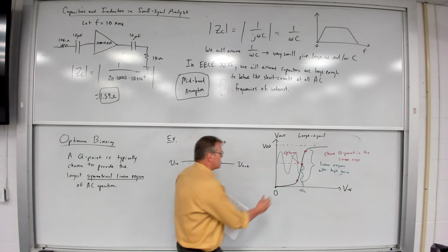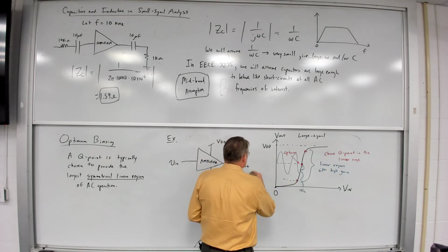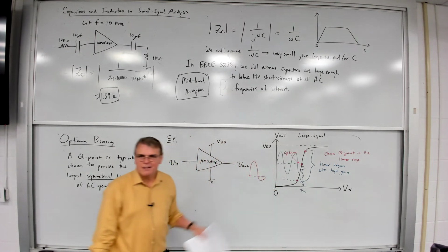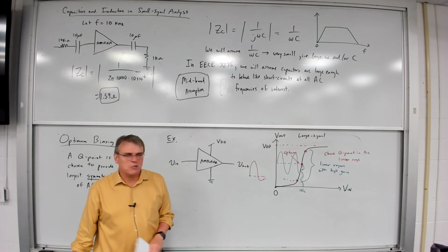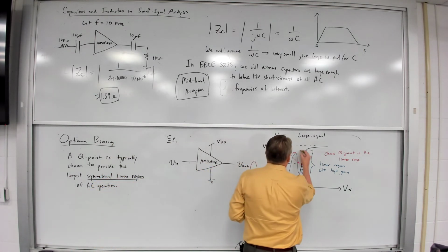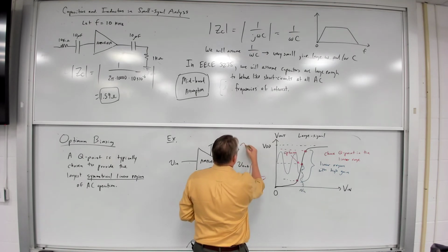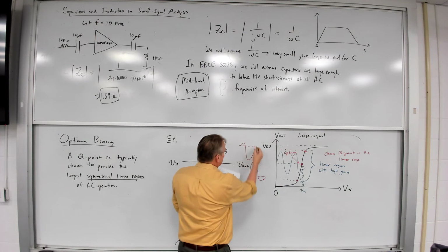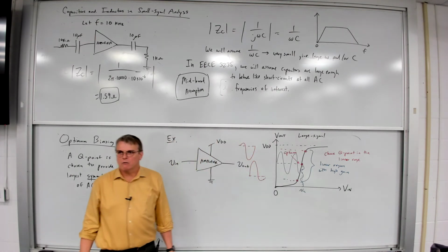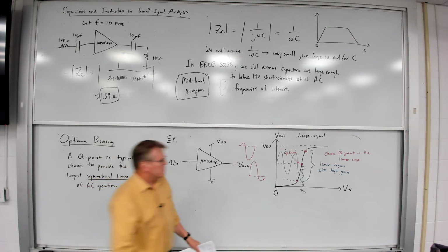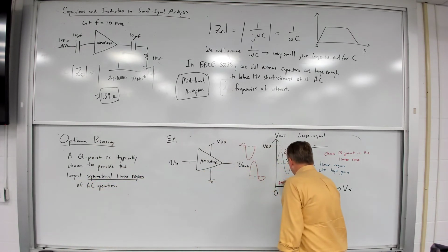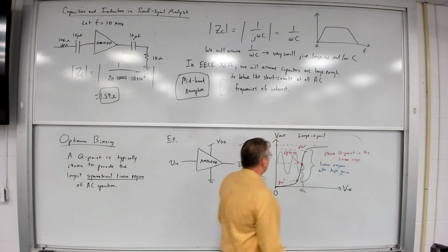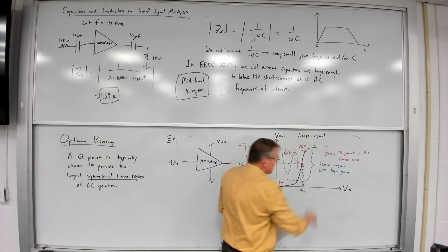If you're down here, you'll have a nice upper waveform, but one that's distorted on the bottom because we run out of room, and the amplifier starts to saturate. Or I could pick up here. In this case, I'll have a nice, strong lower range, but it starts to flatten out on the upper range and begins to distort because I run out of room. The amplifier saturates. So I can choose these, but these are poor. These are not good points. Typically, you want something in the middle.